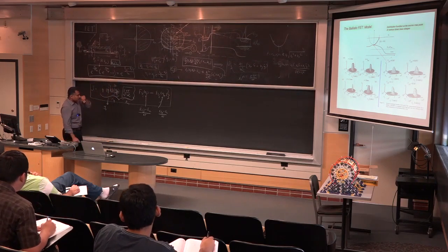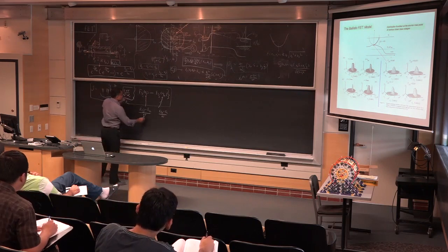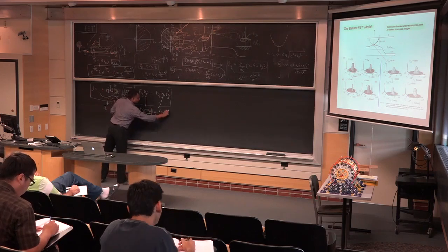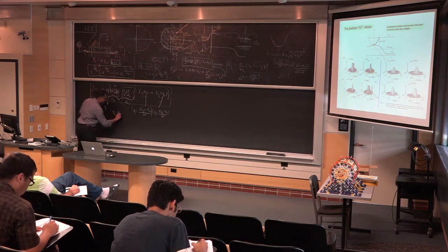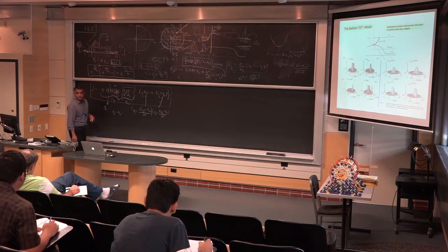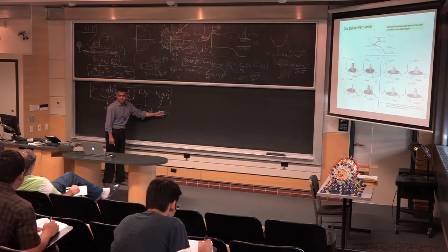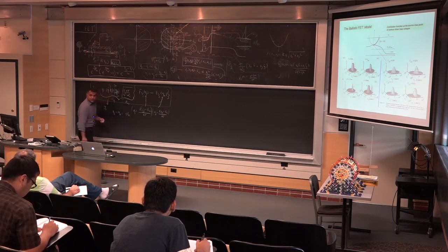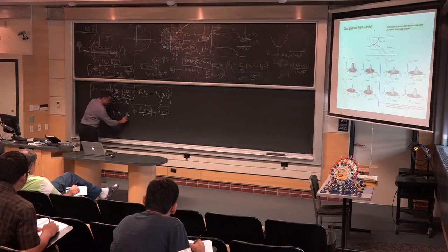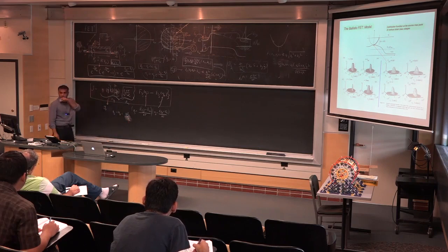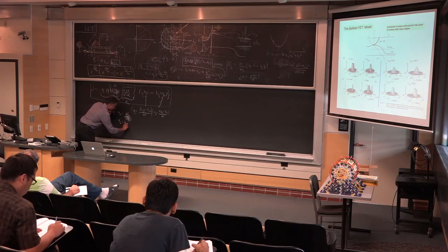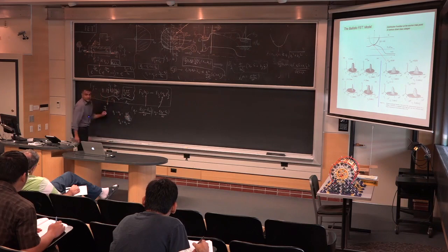It's just equal and opposite. That's what it means. And now you see that if I take, so that's eta sub s and that's eta sub d. Okay. What's the difference, right? So eta sub s minus eta sub d. What's that? So, this minus that, right? That's right, and that happens to be Q times the drain voltage over kT, or kT by Q happens to be just the thermal voltage, so that's that, right? And so instead of writing that I have two unknowns, you see that eta sub drain is just eta sub source minus this quantity.